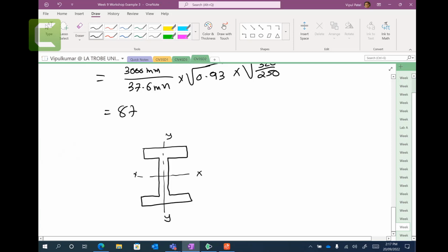So look at these guys. Larger area is distributed far from the x-axis. If I sit close to here, then small moment of inertia. The distribution of the material from the axis, that's how you do it. So this is larger moment of inertia, right?